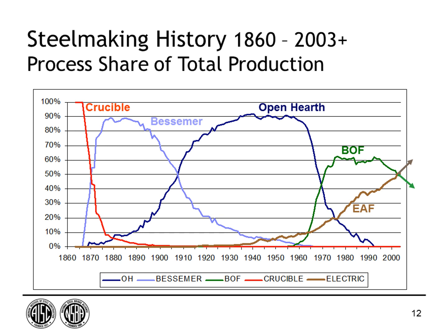If we look at historically how steel was made over the last 200 years or so, it started off with processes that made small amounts of steel, and then we developed in the mid 1940s, we were doing it all with open hearth. Then we had the basic oxygen furnace come into play. But now you see trending is the electric furnace steel, and this is the steel that used to be called mini mill steels because these were small mills that made it basically from scrap, and so they didn't use iron ore as a major ingredient.